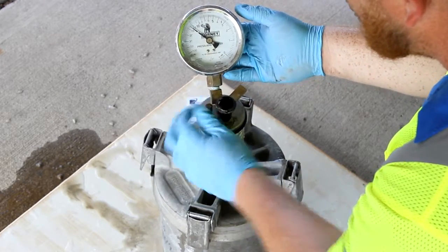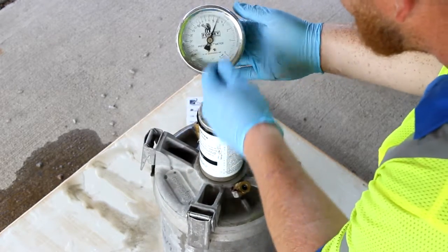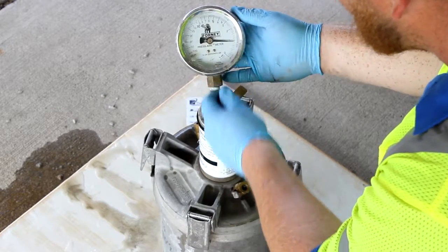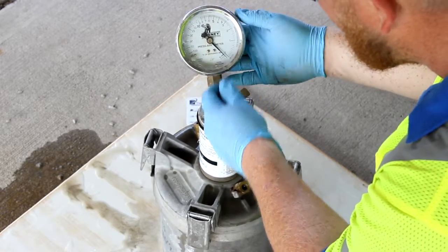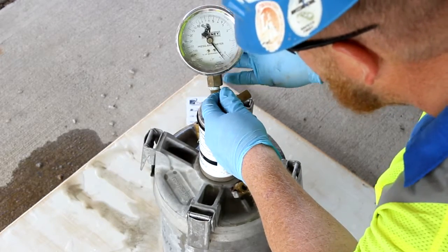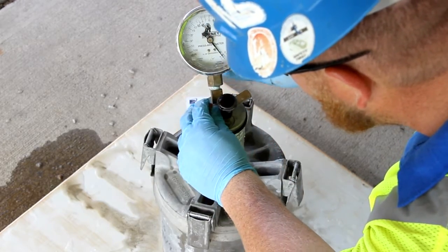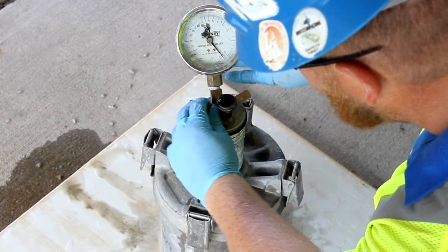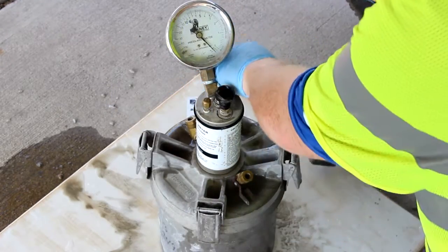Close the air bleeder valve on the air chamber and pump air into the air chamber until the gauge hand is on the initial pressure line. Allow a few seconds for the compressed air to cool to normal temperature. Stabilize the gauge hand at the initial pressure line by pumping or bleeding off air as necessary while tapping the gauge lightly by hand. Close both petcocks.